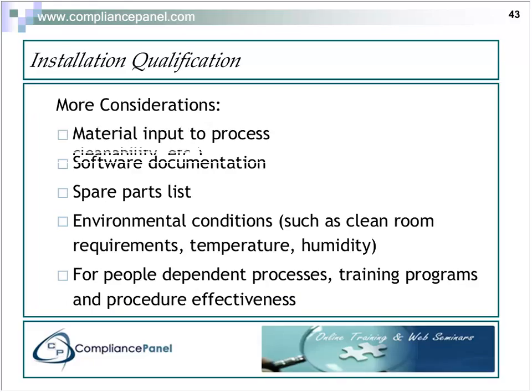What kind of material is going to be input to the process? Are we using titanium, aluminum, plastic? What is the input? What kind of software is included? What kind of spare parts do we need to keep this thing functioning around the clock, producing our product? What kind of environmental conditions are associated here? Is there a clean room required? Is there a temperature range and humidity range for the process? And what kind of training program and procedures are required for the operators?